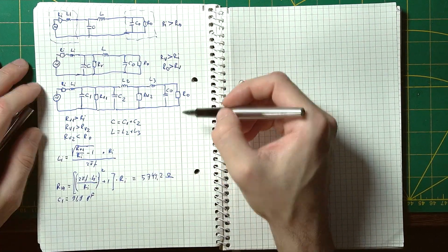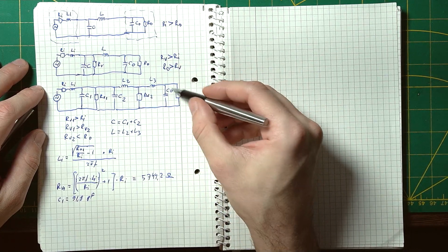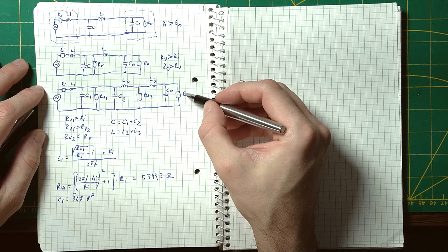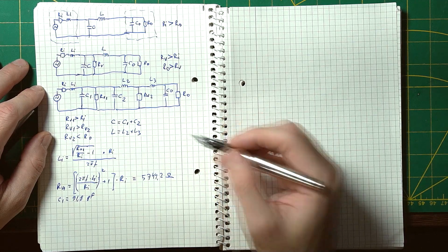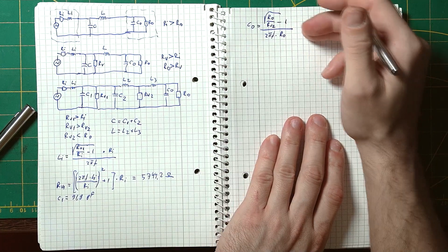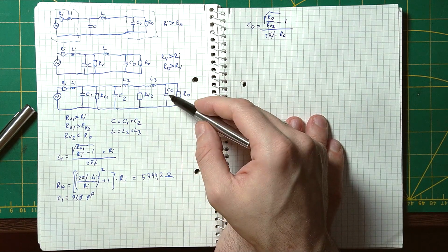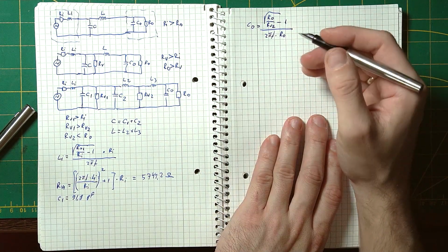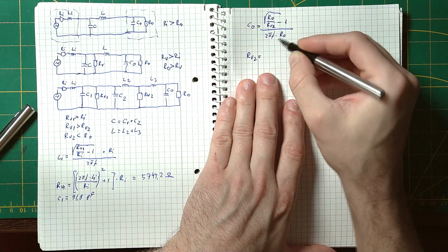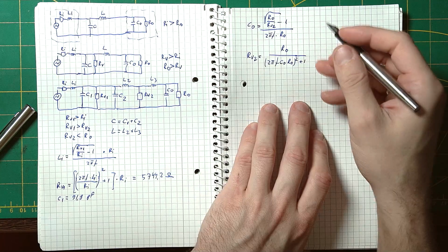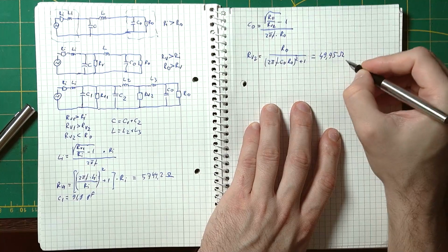Let's move forward. We can now look at the last matching network, where again we know two of the terms, the output capacitor and the resistor, and from here work out what our second virtual resistor would be. Based on the formulas from last time, this would be the relationship between the two resistors and the parallel capacitor. Again, if we turn things around a bit, we can work out the resistor value, and if we punch in the values, we get a resistor of 49.95 ohms.